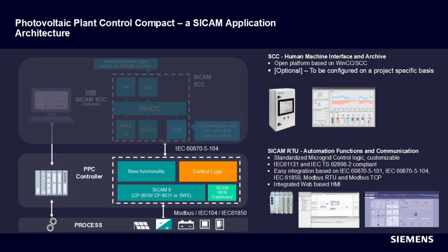This solution begins at the process, focusing on what we are controlling and monitoring. In this case, we concentrate on photovoltaic type converters while also integrating power meters, weather stations, and potentially protection devices, all using standard communication protocols such as Modbus, IEC 104, and IEC 61850.